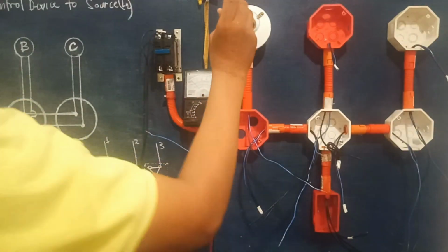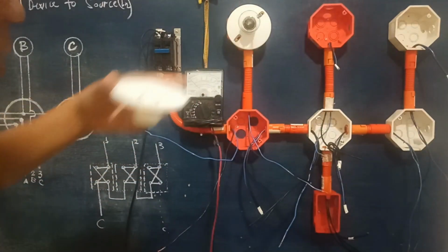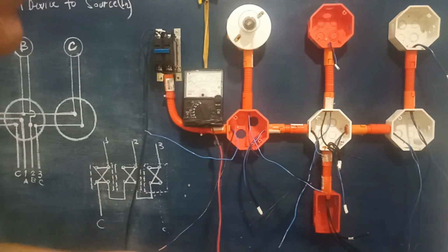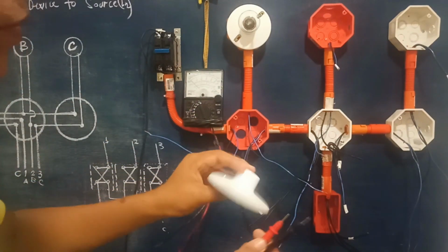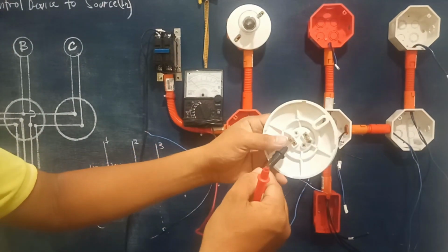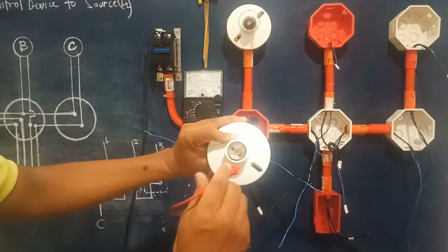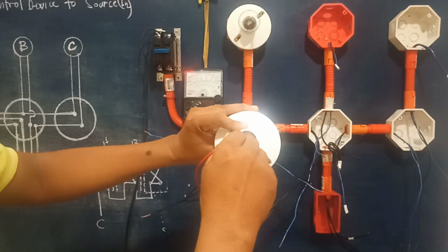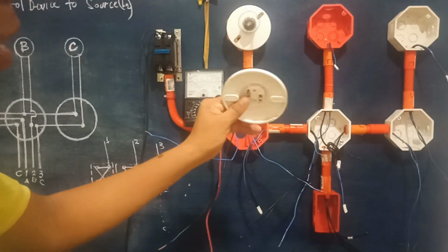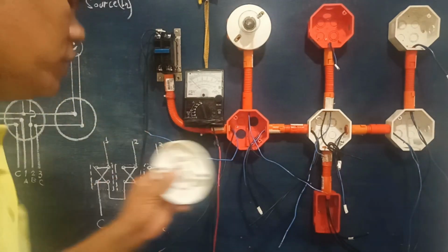Okay, then do the same process right here. Find it first as to where is the location for the connection of our neutral line connections right here. So just do this one right here, then test right here. So since this is the one, meaning to say this terminal here is intended for the ground line connections of our lamp holder this way.